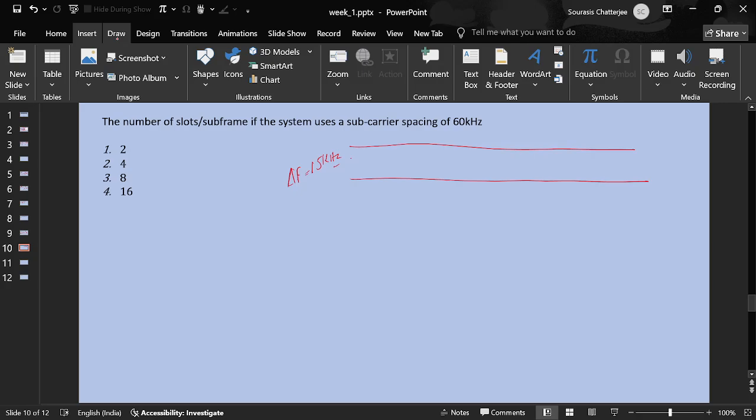Okay, in 5G you actually use dynamic subcarrier spacing, true, but in 5G you are also looking at two bands. The first one is called FR1, which I am sure you have gone through. This is also called the sub 6 gigahertz band, that is anything below 6 gigahertz. That is FR1, and here the maximum bandwidth allowed to you is 100 megahertz.